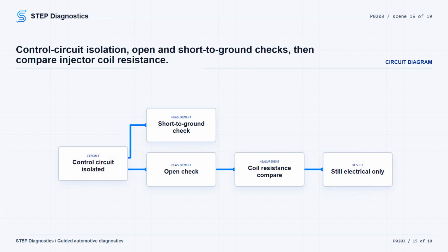Fuel injector resistance is typically between 9.0 and 18.0 ohms. Typically, the difference should be less than 10% between the injectors, and during this DVOM coil check, the resistance value should be within 10% of the other fuel injector coil resistance values. This coil resistance check is only an electrical check. It does not prove the injector is moving mechanically.